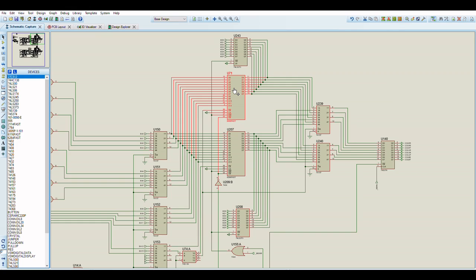So I doubled the RAM for the tile definitions, but it did mean that I had to introduce a little bit of extra complexity in terms of deciding which RAM I wanted to select for reading or writing the tile data. But eventually it then goes through to this demuxer here. So the output buses go through this demuxer here.